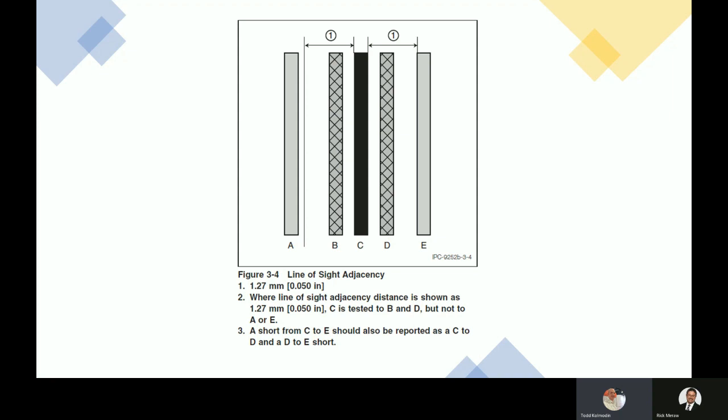In a fixture test, the full parametric test, if the distance between net 1 and net 2 is 1 inch or 3 inches or 5 inches, it's still tested in the isolation or shorts algorithm to net 1.